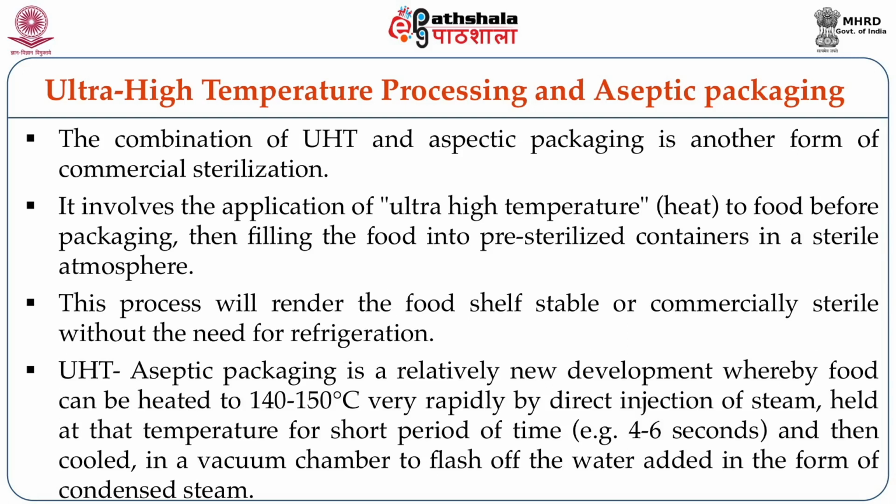Ultra-high temperature processing and aseptic packaging is a relatively new development where the food is heated to 140 to 150 degrees centigrade very rapidly by direct injection of steam, held at that temperature for a short period of 4 to 6 seconds, and then immediately cooled in a vacuum chamber to flash off the water added in the form of condensed steam.